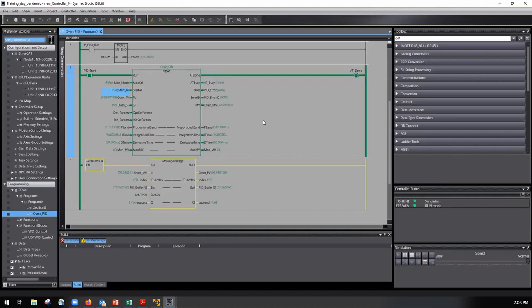It'll jump around a little bit, but it was very quick in the simulator because my feedback loop was too perfect. It's not really real world conditions, but you can see all of my parameters now, my P band, my I time, my D time, they've all been tuned. They've got 60 milliseconds on my D time. I've got 1.4 seconds on my I time, and my proportional band has settled on 515.